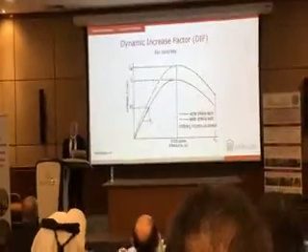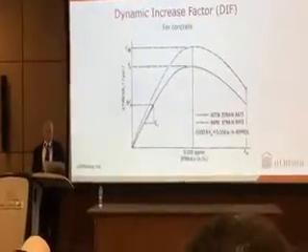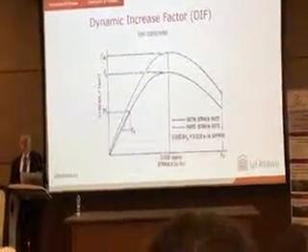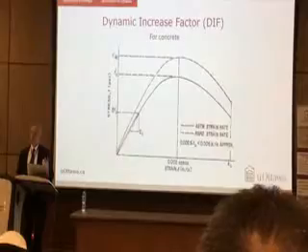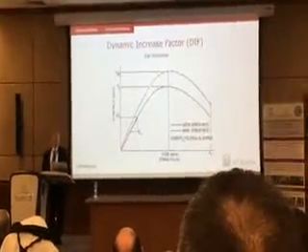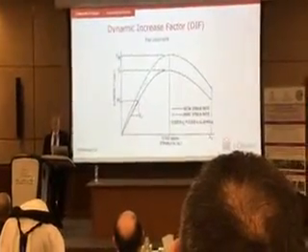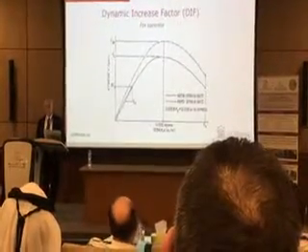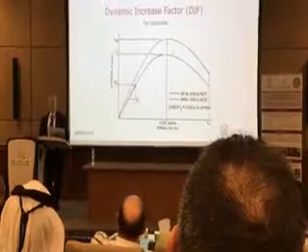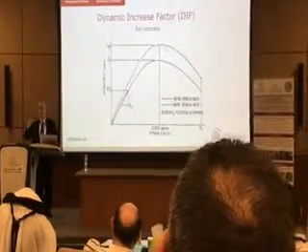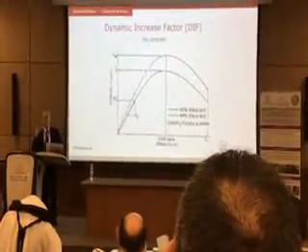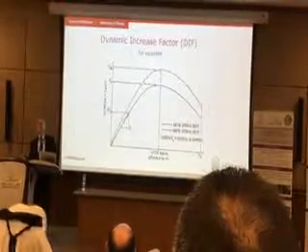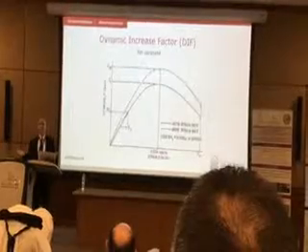Okay? So if you put your cylinder, or I don't know if you do cube testing here, but your concrete sample into a machine to establish its strength, then you get the solid line, which is under static loading, right? It takes maybe 15, 20 minutes to finish the test. But if you apply this load very rapidly at high strain rates, the strain that you induce is very high, as in the case of blast, material doesn't have a chance to fail.